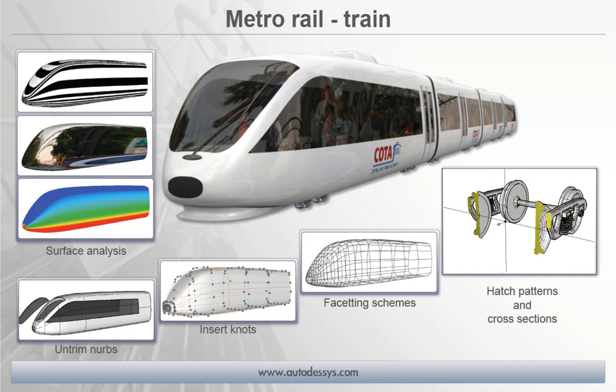The Insert Knot tool, which gives you the ability to insert controls anywhere you want on the surface without altering the surface at all. It actually adjusts the positions of the other controls to maintain the surface exactly the way you want, and we'll look at that in just a moment. There's also new faceting schemes to ultimately control the faceted representation of your smooth objects, including non-triangulated quads.